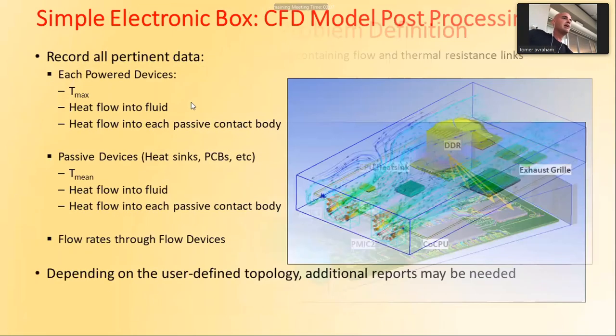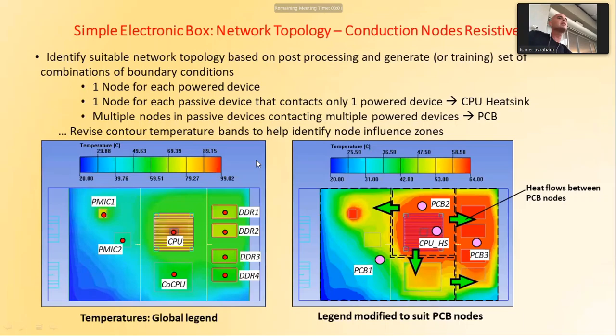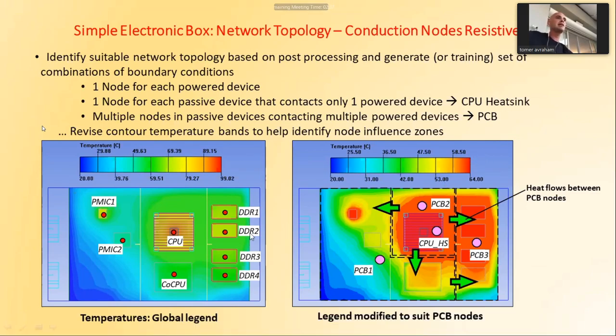And what we get is kind of a division of areas, a map, still a CFD, resistive links, one node for each power device, and passive devices if we want to extract details for reliability, the memories, everything is here.